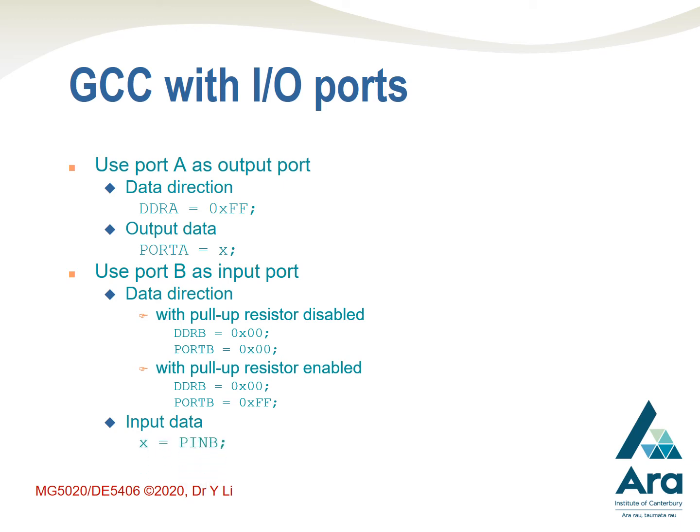Then we can read the port by using a statement like x equal to PINB, which means to get the value from the right-hand side, which is PINB, and then assign the value to the variable on the left-hand side, x.